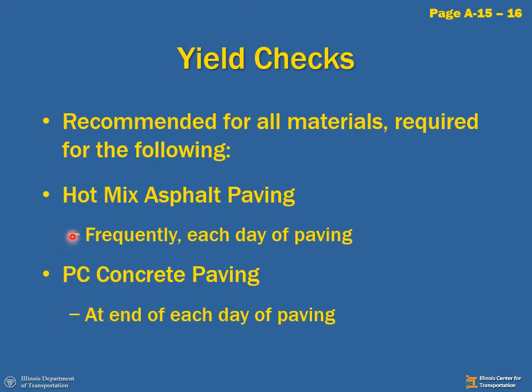For hot mix asphalt paving, yield checks are required frequently during each day of paving and an overall yield check at the end of the day. For concrete paving, at the end of each day is the only requirement by spec.